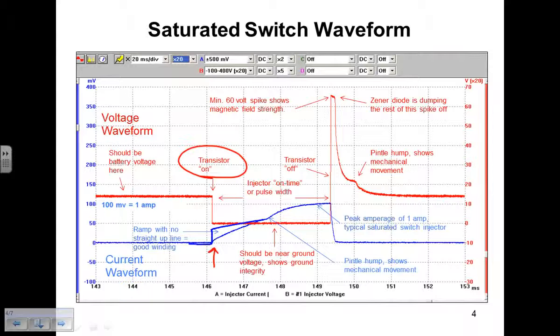Okay? In the 20 years I've been doing this, the only injectors that I see do this are the Multec ones. GM, right? Early model GM vehicles. Major problem with shorted injectors. That would be a partial short. As they got worse, this line would increase further, and then this, of course, would climb. And I've seen them where they'll pretty much be something like that, which is a completely shorted condition, overloads the driver, causes the car to shut down because they were group-fired systems. But we want to see a ramp.